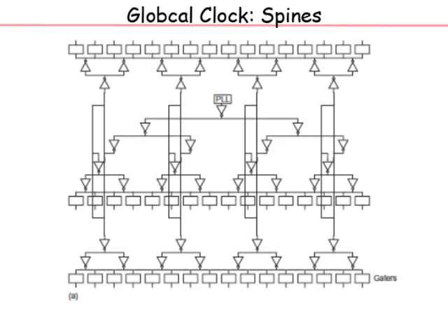What that does is that the effective edge out here becomes an averaged edge. So one edge comes a little early, one comes a little late. The actual signal out here would be an interpolation between the two. So you have an effective edge which happens on this node, which is in between. It's an average of the arrival time of the edges at all of these nodes.